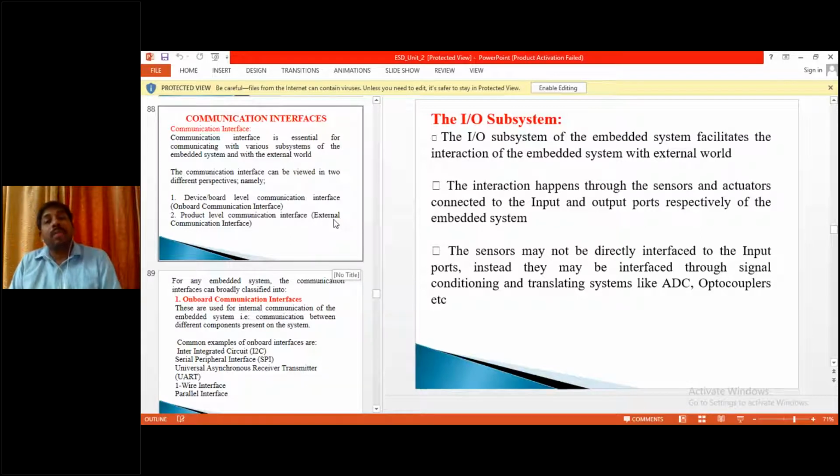So the processor logic, the control element logic, is that they just take the difference of the temperatures, room temperature and the temperature set by the user, and they just generate a signal to be sent to the actuator. That actuator will run the motor fast or slow such that cooling is given to the room.